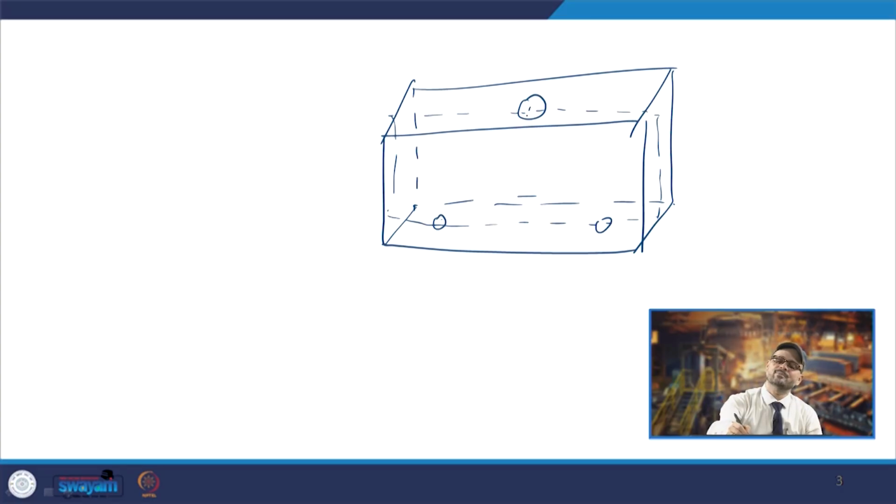Again, in such kinds of geometries, you can have further bifurcation from half, because again this is the mirror geometry of this part. So, you can have the solution only for 1/4 of the domain. So, your computational time becomes 1/4 of what you were doing, and that is helpful when you are doing these analyses and solving the equations.